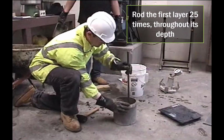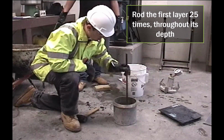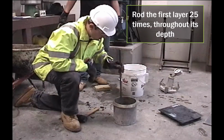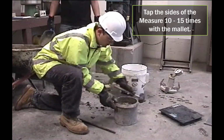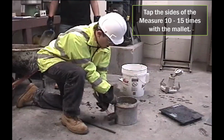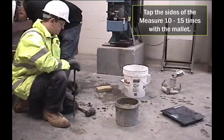We can now rod the first layer 25 times. As always, we'll use the rounded end of the tamping rod. We'll rod the first layer throughout its depth, without forcibly striking the bottom of the bowl. Now, tap the sides of the bowl 10 to 15 times with a mallet, using such force as to close any voids left by the tamping rod and to release any large air bubbles that may have been trapped.